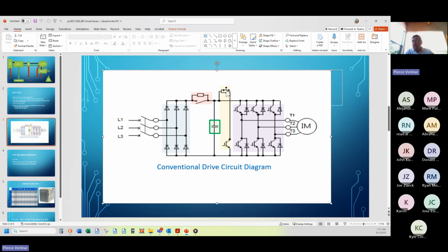And if there is a resistor externally connected to this transistor, the 7th transistor, the dynamic braking transistor, it will shunt this resistor across the DC bus, and this resistor will start to absorb energy. So rather than letting the DC bus fly up to 820 volts and overvoltage tripping, this transistor starts to fire and hopefully can send enough energy to the resistor bank to prevent the voltage from increasing to the overvoltage limit.